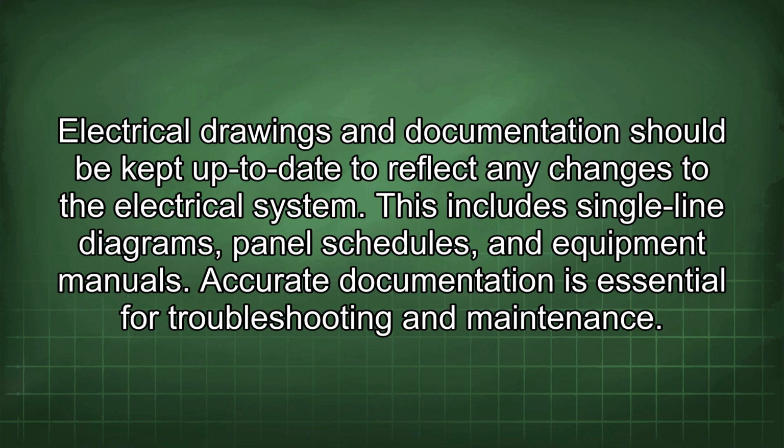Electrical drawings and documentation should be kept up to date to reflect any changes to the electrical system. This includes single-line diagrams, panel schedules, and equipment manuals. Accurate documentation is essential for troubleshooting and maintenance.